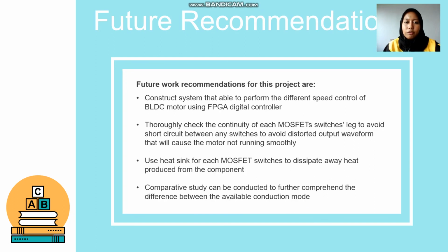And finally, for the future recommendation, it is recommended to construct systems that are able to perform different speed control of the BLDC motor using a digital controller. Next, it is advisable to thoroughly check the continuity of each MOSFET switch leg to avoid any short circuit between the switches, to avoid a distorted output waveform that will cause the motor not to run smoothly.